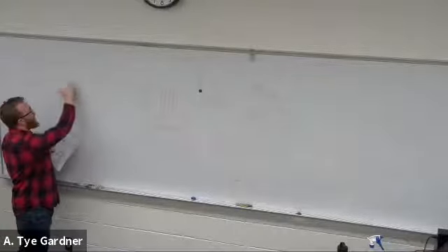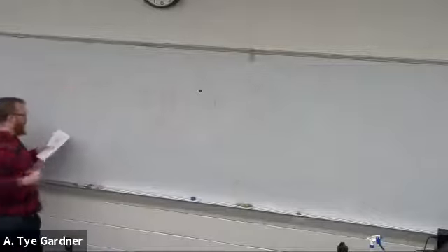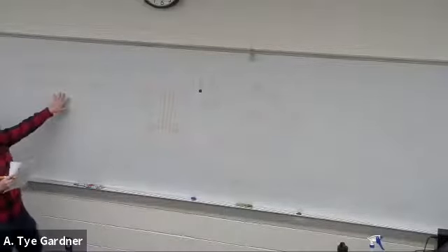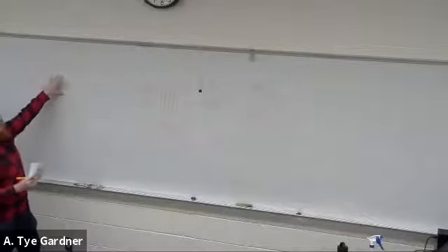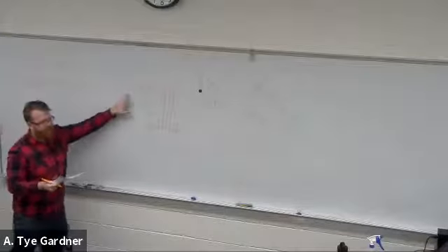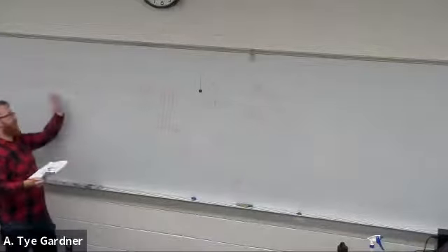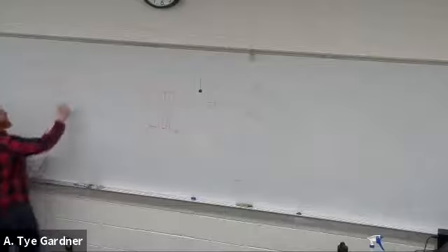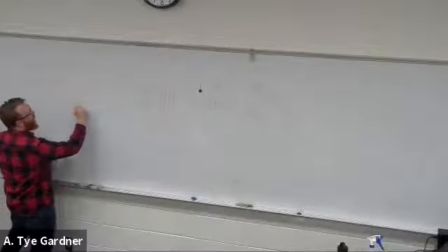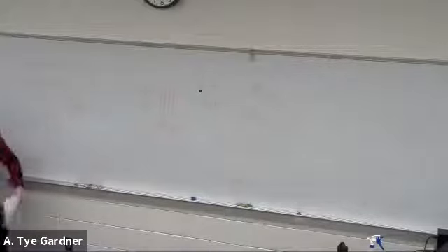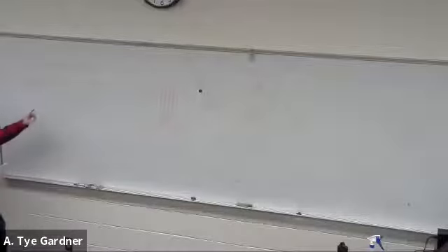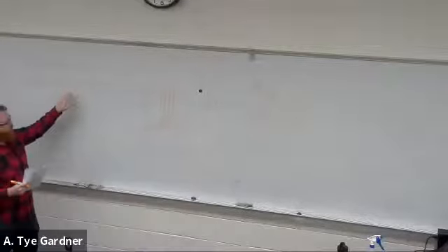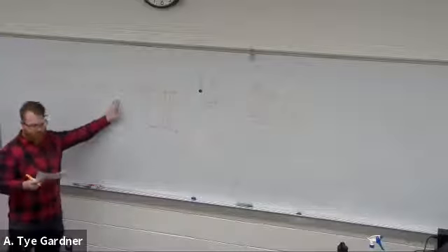It's not R of epsilon, this is R. I mixed 2 equations there. So why I wrote R of epsilon is because if you take R of epsilon multiplied by the temperature, that's what we're doing. And then the second equation that I wrote down is just this, where we're taking R naught, which is R of epsilon, right? A function of strain. So we're really ending up with a multiplicative error at our input, right? That is the multiplication of the effective strain by the effect of the temperature.